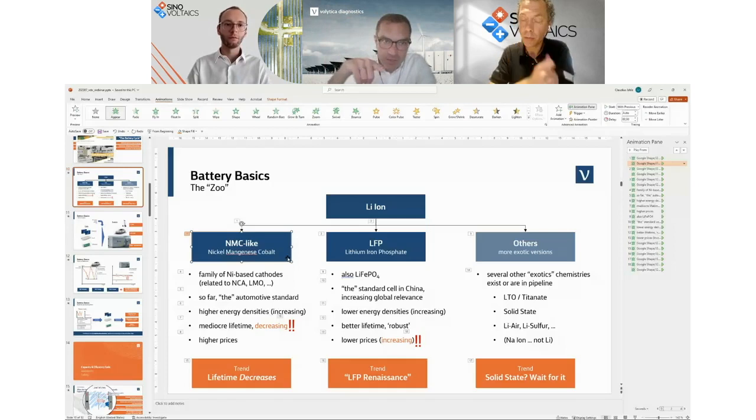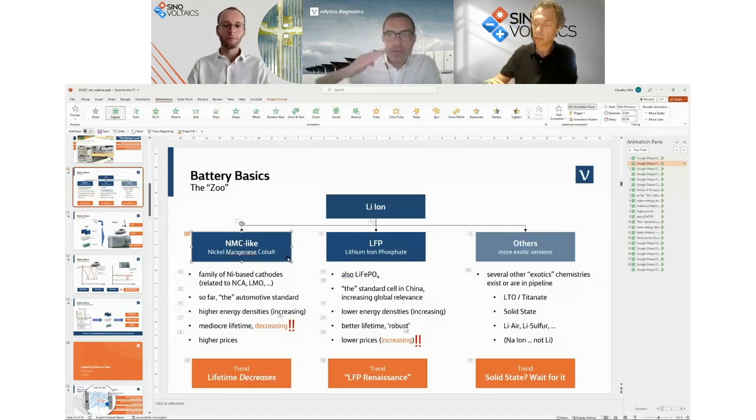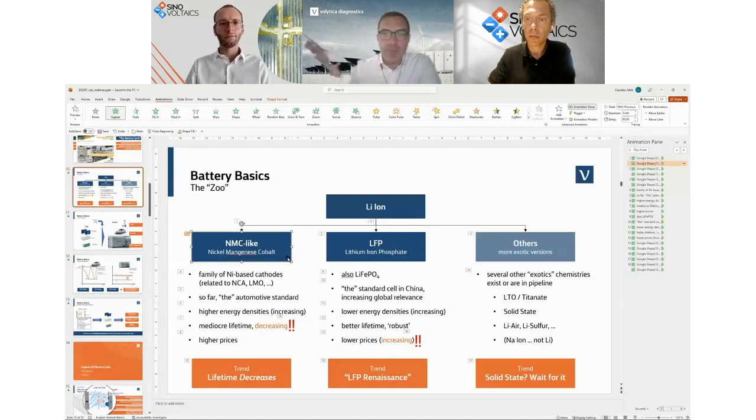Charging is important. Charging at 1C when the temperature is lower than 20 degrees or 15 degrees is not good, because this is one of the situations that can facilitate lithium plating. So under 1C, you're happy, and over 1C, it depends on the exact chemistry that you're using.